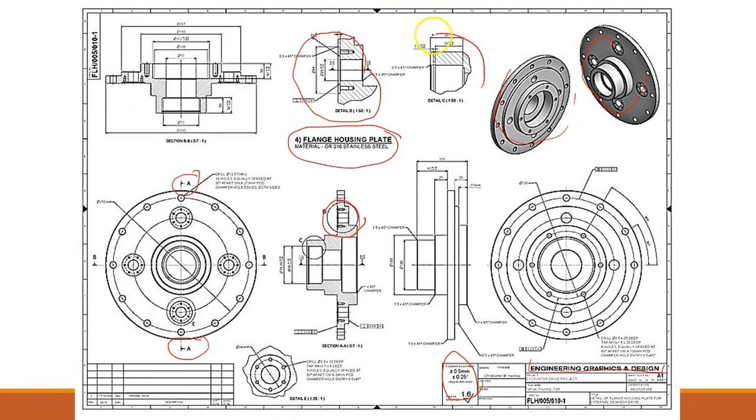We got detail C, which depicts this portion here. Because these are such small portions, we can now see what these snap rings look like. We can see much smaller and tighter tolerances. We can get more information on what might be an O-ring or a chamfer area inside of here that we couldn't have seen inside of this drawing.